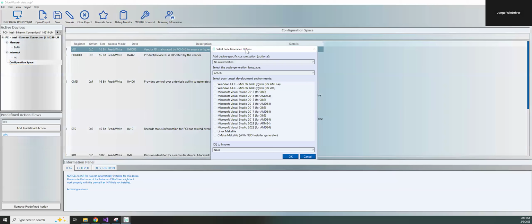Okay. In this window, we can choose a device-specific customization. What does that mean? Our development team created specific samples for Altera and Xilinx DMA designs, IPs, okay? So for Xilinx, it's the BMD design, the QDMA and XDMA, and the Altera Avalon only memory mapped, okay, IPs.